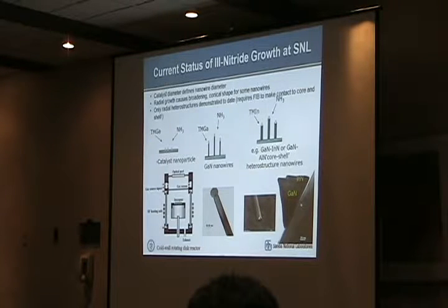So let me talk about growth. I think virtually everybody here has probably heard about VLS growth, vapor, liquid, solid. I don't actually believe it's vapor, liquid, solid. I think a lot of evidence right now is that it's actually vapor, solid, solid. But that's for III-Vs. For III-Vs, yes. So I think for III-Vs, this is what we see with gallium arsenide. It's what we see with gallium nitride. But the basic growth goes as a catalyst metal. Often it's nickel.